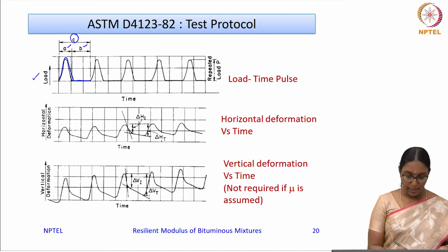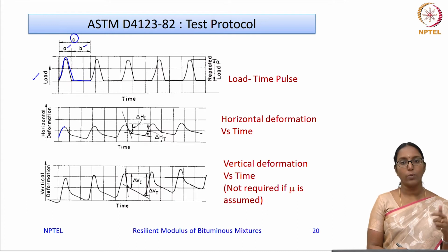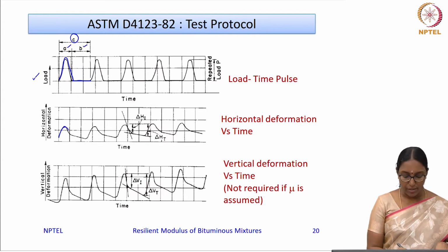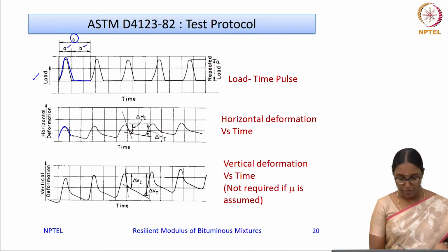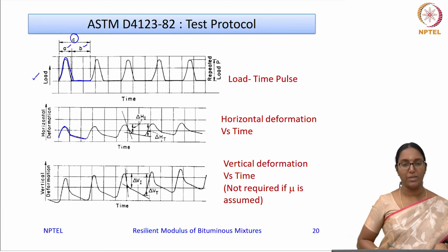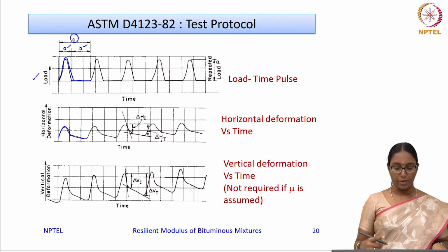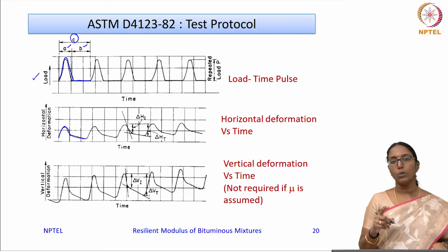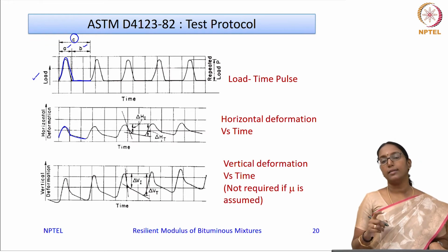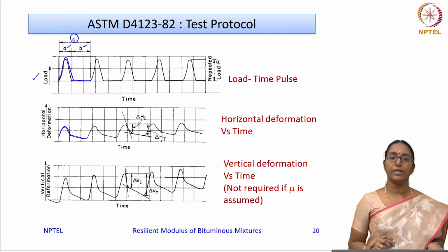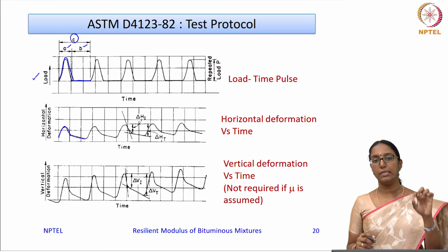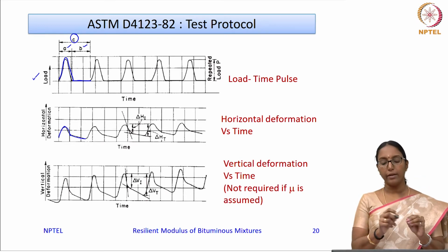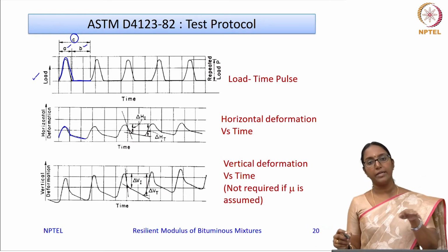figure you can see that as the loading increases, your deformation increases, and when it is unloaded, the deformation decreases, and during the rest period also there will be recovery of deformation. So, you see a recovery of deformation here. Okay. This continues, and what we are looking at is there is certain amount of instantaneous recovery that happens. So, when one starts unloading, there will be instantaneously a recovery, and during the rest period there will be a continued recovery.